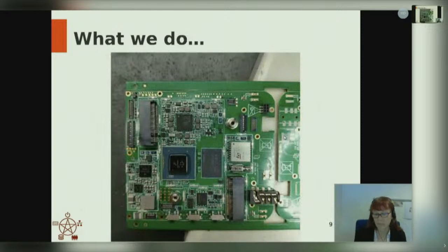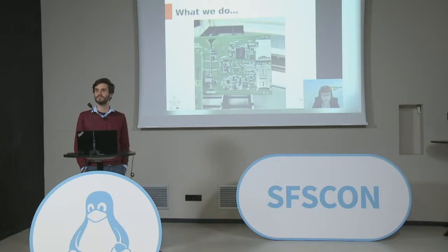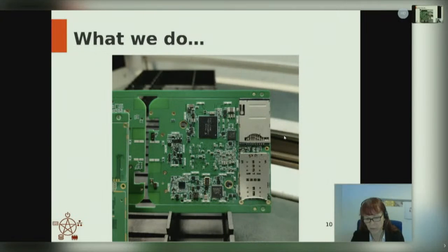And later on, during the next year, we started the development of the real smartphone main board. And this is what you can see here. So that's the front side of the main board with the 2 M.2 slots here on opposite sides. In the center, there's the main CPU, the NXP i.MX8. That's the eMMC. Here's the GNSS, vibration motor, and things like that. And that's the backside of it with these slots for the SIM card, and also the micro SD card. The RAM is here, and that's the PMIC here. Oh no, that's a USB hub actually down there.